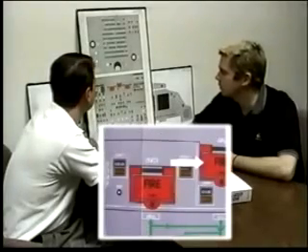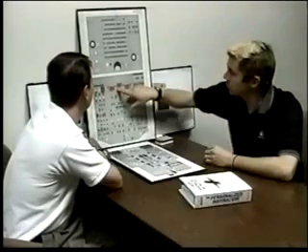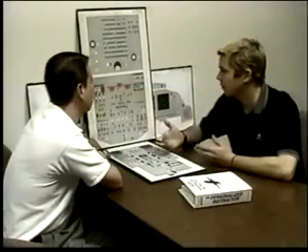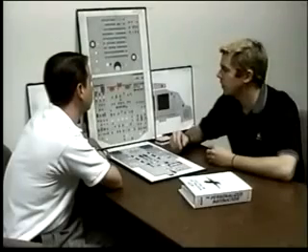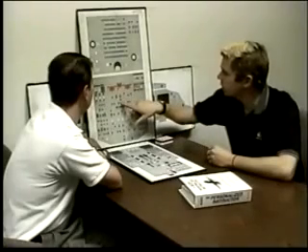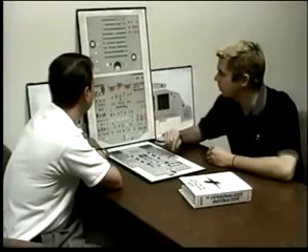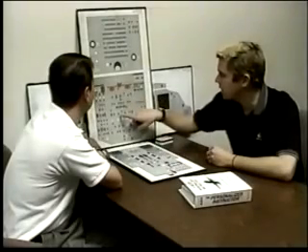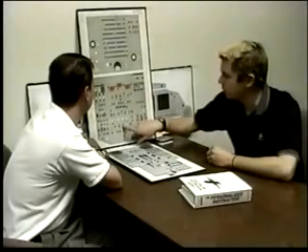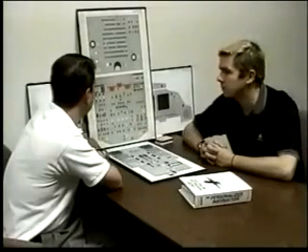What about for the APU fire push button? APU, we can still use 21212. It's just a little bit more awkward. First of all, we'll arm the squib and still silence the warning. There's nothing hydraulically that goes on, but we have to remember that it shuts down the APU using the ECB, and what that does is it sequences the shutdown for us. The fuel, it shuts off the APU fuel pump as well as closes the fuel line. And the electrical, it deactivates the APU generator. And on the air conditioning, it closes the APU bleed valve. And because this valve is closed, and if this is on auto, the cross bleed will also close.